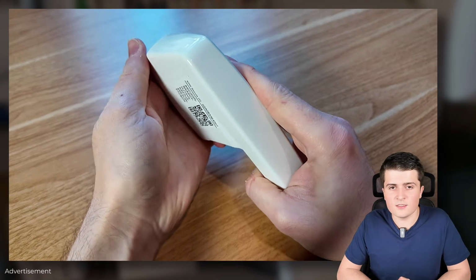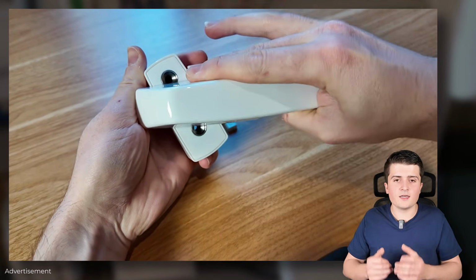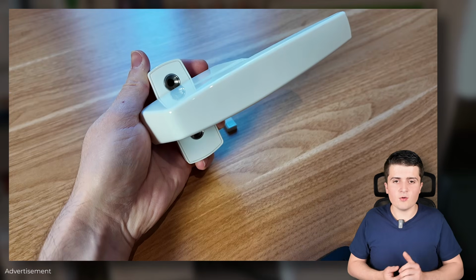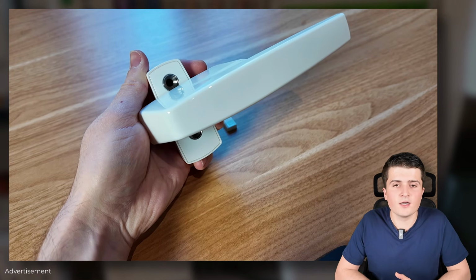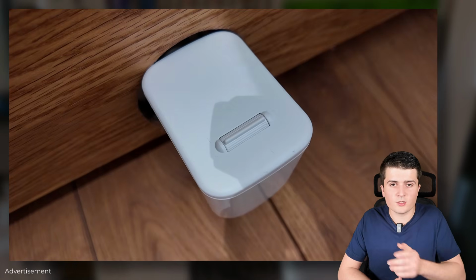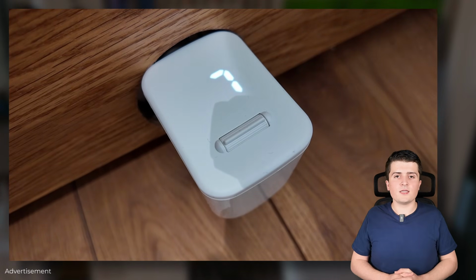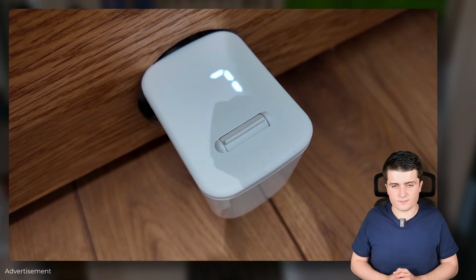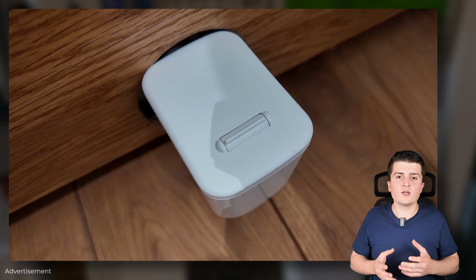And with that, if I download everything and I now open up this window handle, you can see if I go to my thermostat that it's now in frost protection mode, because we can see the set point is now 7 degrees Celsius. So this is how you can also combine multiple RF Multi devices with each other.